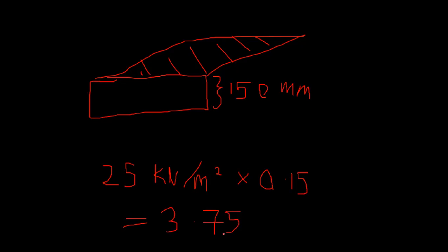Remember, we have neglected the weight of the beams and columns. We are not modeling the slab, we are giving the weight of the slab. We model the beams and columns but set the self weight to 0. That means the results come only from the self weight of the slab and the live load on the slab, not the weight of beams and columns. If you want, you can set that self weight multiplier to 1. Okay, then that's done.